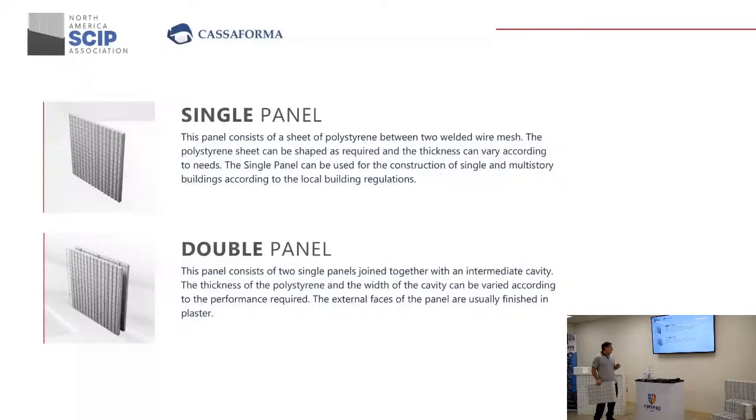The double panel has usually been used when you want to get over 4 stories, like 5 or 6. There are countries that will allow you to do that with a double panel. It was originally invented for Antarctica, because there was a need to get it done quickly. You pour the concrete in the center, and then you leave the other side until the climate allows you to build it over. That was back in '88.